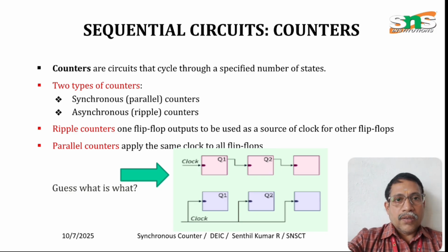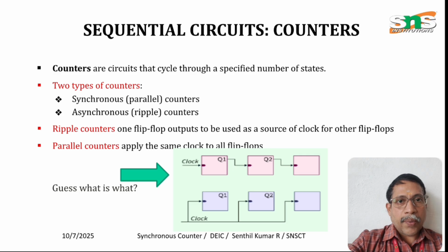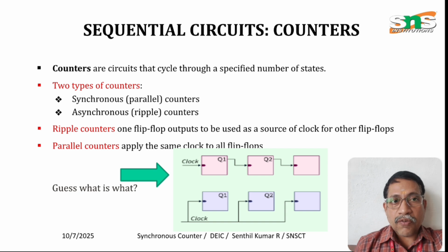See here, the circuit is given. As per the discussion, the pink color basic building block is nothing but the flip-flop. There are 3 flip-flops, whereas the clock pulse is given to the first flip-flop. The output of the first is given to the input of the second as a clock. The output of the second is given to the input of the third as a clock.